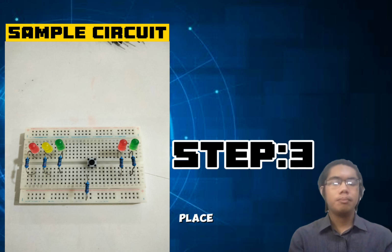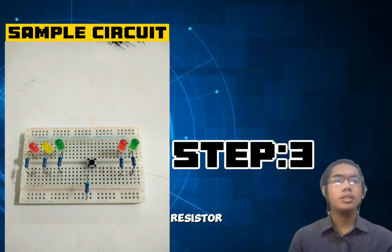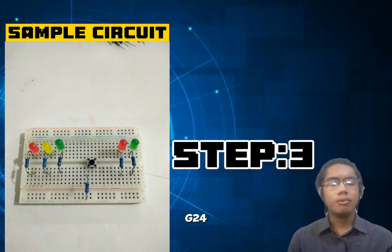Step 3. Place all resistors on the breadboard. In car red LED, place the resistor between E28 and G28, E24 to G24 for car yellow LED, E21 to G20 for car green LED, E6 to G6 for pedestrian red LED, E3 to G3 for pedestrian green LED. And for the push button, connect one side of the resistor from J14 to the positive rail.